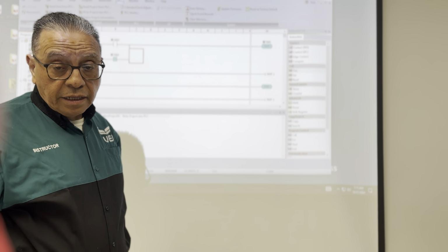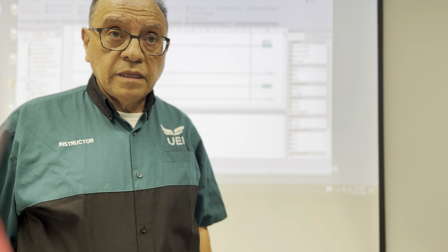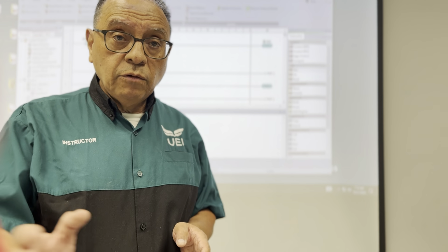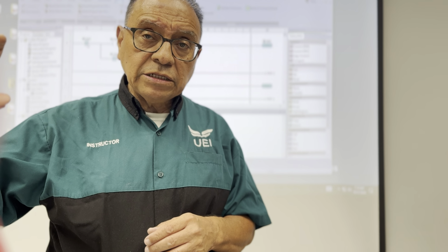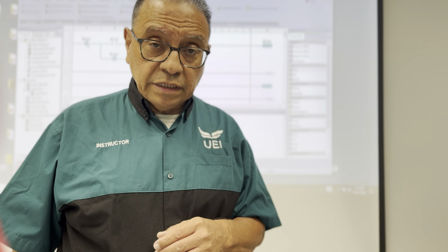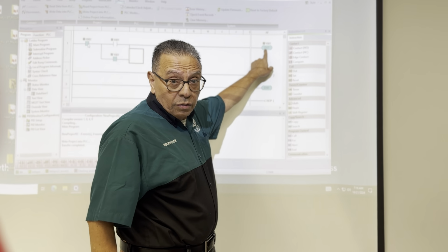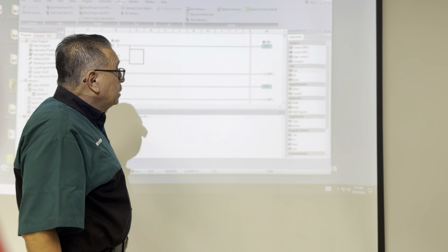This is a typical behavior of the push button station, in which you have the red one as stop and the green one as start, and then you have the contactor that will be energizing and starting your electrical motor. It has an auxiliary contact, an extra contact that is normally open, which is this one. When the contactor coil is energized, this contact is closed and holding the output.